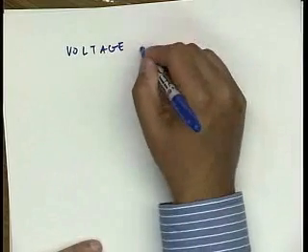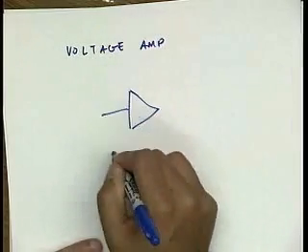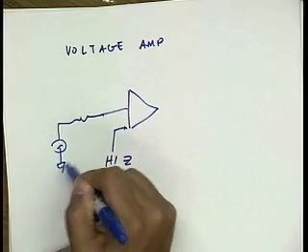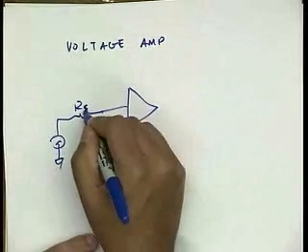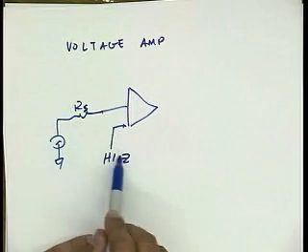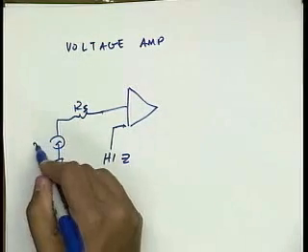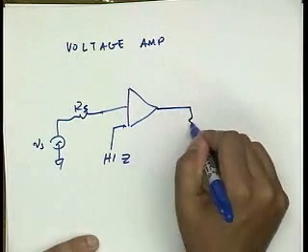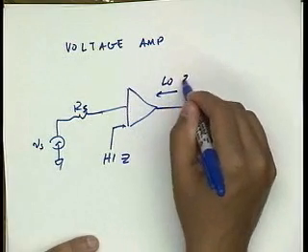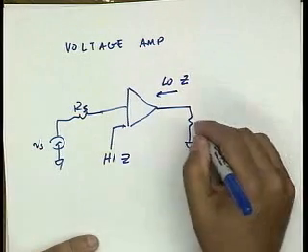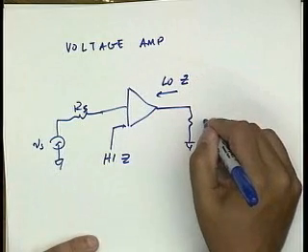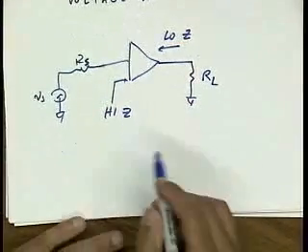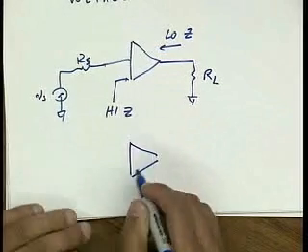So as you guys all know, a voltage amplifier has a really high input impedance, so let's say high Z. And that means that the voltage gain is more or less independent of the source impedance you drive it with, because of this high input impedance, almost all the source voltage Vs appears across the input and gets amplified, right? And likewise, a good voltage amplifier has a low output impedance so that it can drive the full output voltage across the load, no matter what the load value is, right? Now, the opposite is true, of course, for a current amplifier.